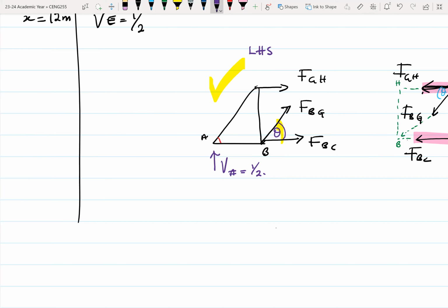Do we consider the direction of the arrow for which we take the reactions for the horizontal and vertical forces? So let me get the question right. What I understand by your question is that, by convention, normally when you are finding reactions, even in year one, you would usually point your reactions to be acting upwards, because normally loads tend to act downwards.